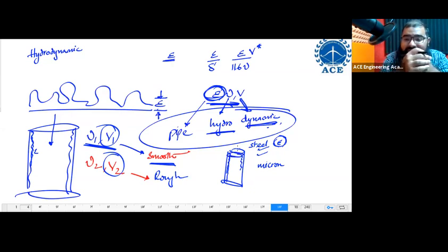So many variables. Finding this average height is not an easy task. One, you are going inside the pipe, a difficult concept. Next, you are measuring something which is in microns. Next, that variation is taking place along the length. It is also taking place along the circumference. All these things make it so much more difficult.